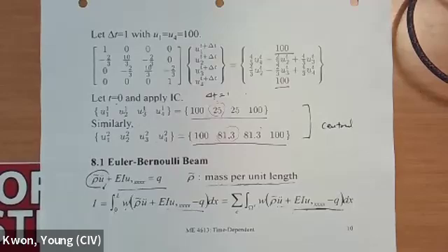In heat transfer, the dot indicates the heat flux rate, and in fluid mechanics, the reason we have a first order derivative is that the primary variable is velocity. So the first order derivative is going to be acceleration, and that gives you inertial force.